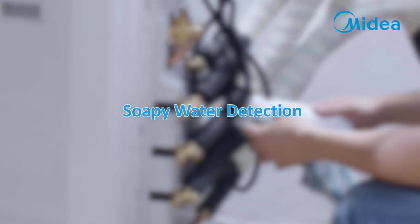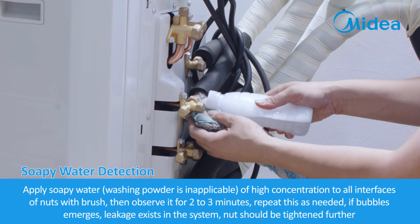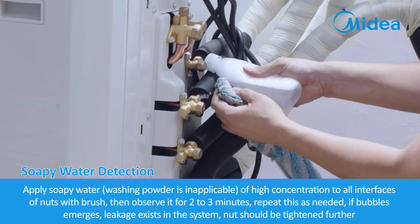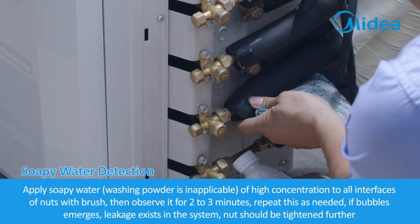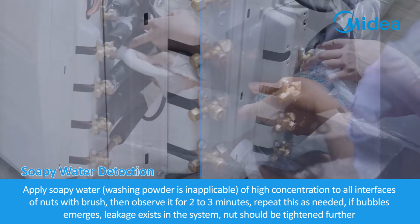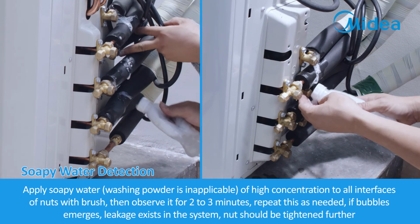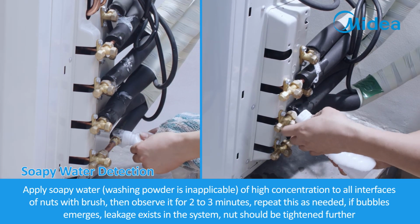Soapy water detection. Apply soapy water. Washing powder is inapplicable, of high concentration to all interfaces of nuts with brush. Then observe it for 2 to 3 minutes. Repeat this as needed. If bubbles emerge, leakage exists in the system. Nut should be tightened further.